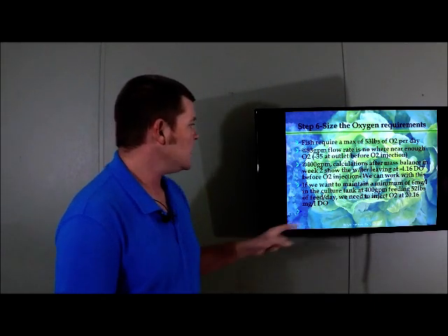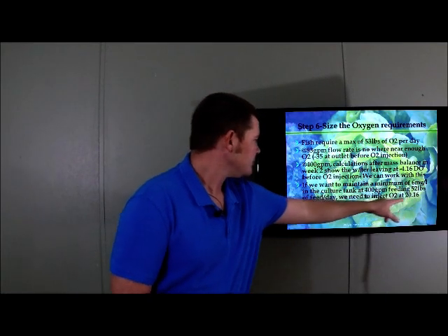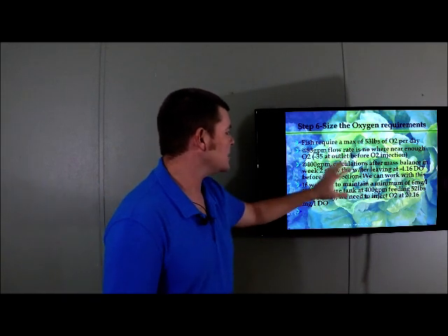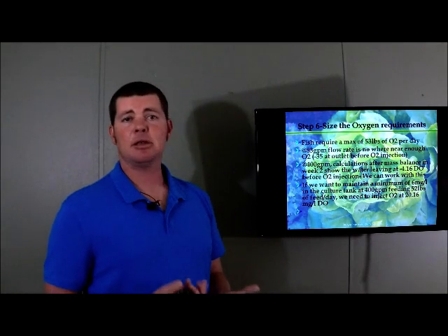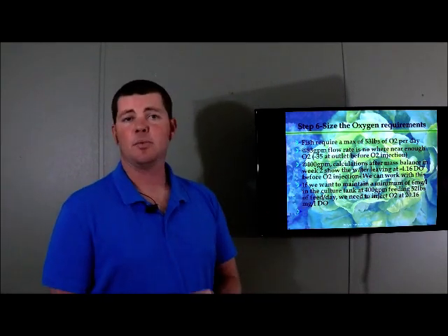All right? So when we inject at 20.16, we're going to use all the oxygen that we've supplied, and the water will leave at 6 milligrams per liter. And that's directly off of the calculations that we learned in week 2.